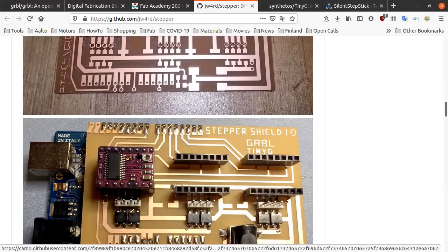So they have a variable setting. There's a little potentiometer there that Chris is showing, where you can set how much current goes there. It's a very handy and precise way of controlling stepper motors, and also a way that keeps the power in control, so it takes care of a lot of the things, like overheating, for you when you work with these drivers.